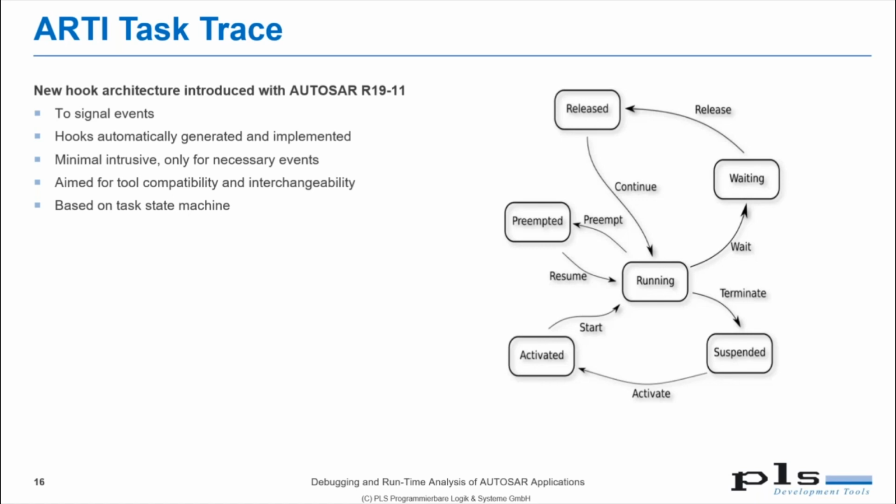Maybe you know a little bit about tracing. Tracing is basically a hardware feature that allows you to observe the runtime behavior of your system. The typical way is to trace the executed instructions and to get the program trace, and from that you can analyze the trace data and see which functions were executed.